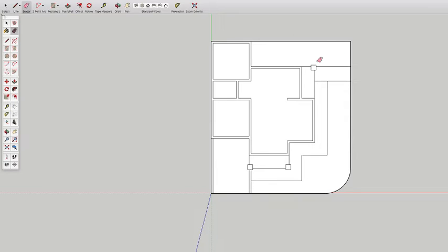And I'm going to offset those walls by 15 centimeter. To do that, I'm just going to go to select tool and select my line, and then hit the offset tool. I set 15 centimeter offset it, and then do the same thing with this corner, offset by 15 centimeter. Like I said before, all of your walls need to be 15 centimeter.